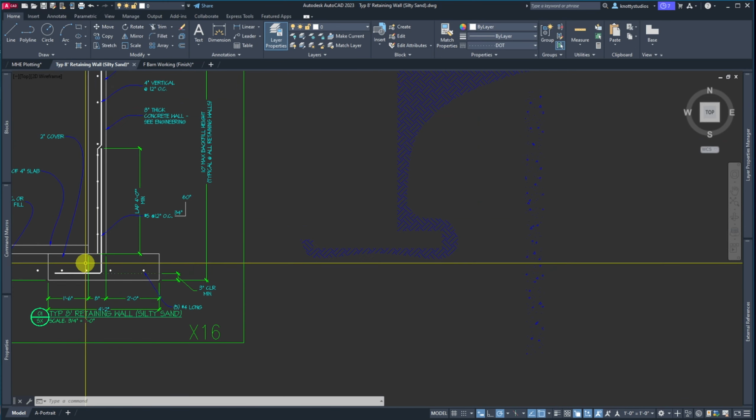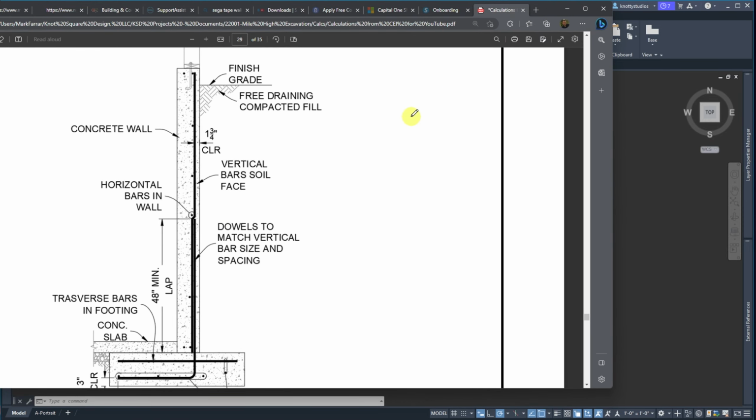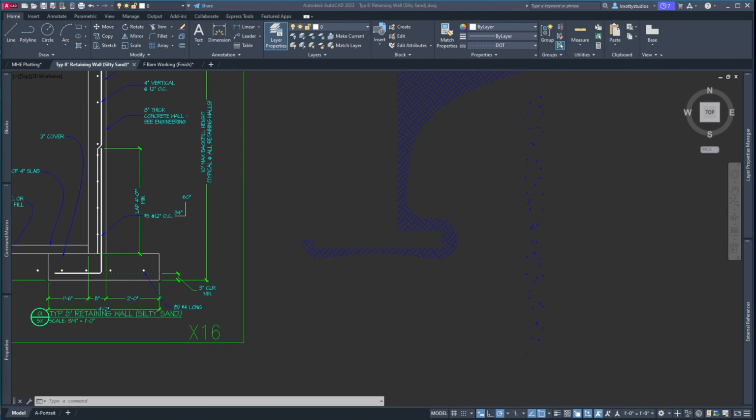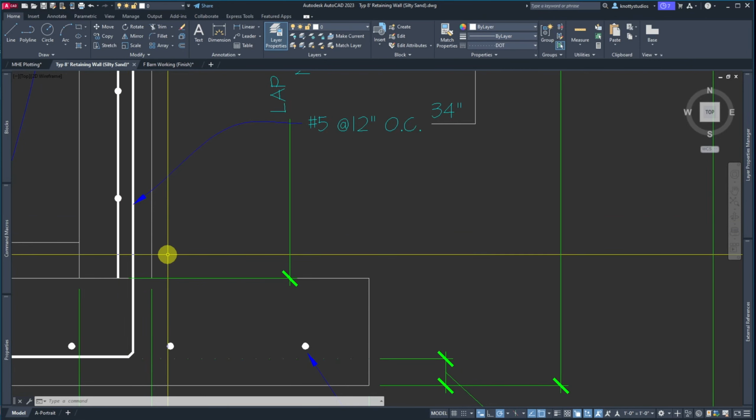So here we need 5, and down at the bottom and at the top we have a bond beam. What that is, we've got 2 rebar here and 2 rebar there, and if this was CMU instead of a solid concrete wall, there would be a breakout in the block where the bond beam or these rebars can run through continuous. There'd be one here, one there. You run those bond beam courses in CMU, but this is solid concrete, so we just have to do rebar placement.